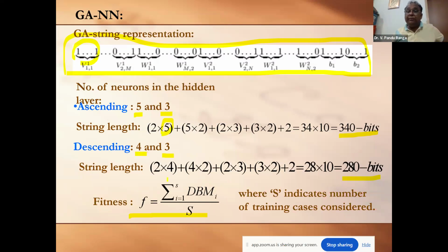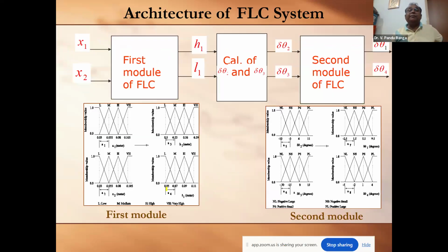As the string represents the motion of the biped robot, overall we are trying to find the dynamic balance margin, which shows the stability of the dynamic balance of the robot when it is working on the terrain. That way we have formulated the fitness function for this problem.